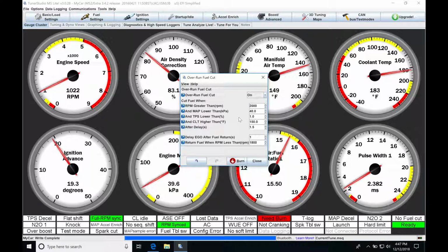But I always suggest that you leave this off, tune your main VE table, come back in, then turn this on and dial it in. You'll find that it's much more effective, and it's much easier to tune your VE table without having to worry about this potentially creating lean conditions as you're dialing in the curve, especially at the low vacuum portions where this has more potential to kick in.